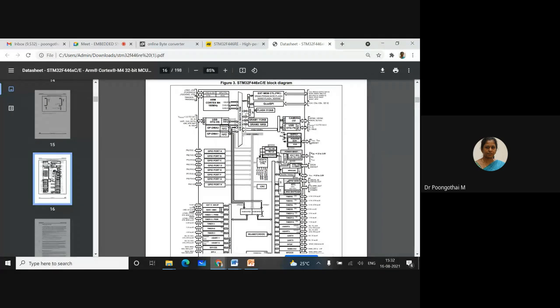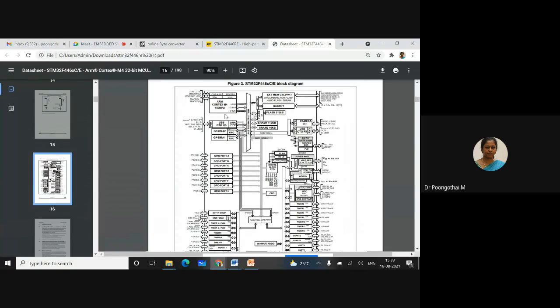All the peripheral devices are connected to this particular processor. The CPU engine interfaces to the ST implementation by using three bus interfaces: I bus, D bus, and S bus. This is the software IP format given by ARM, the intellectual property format, and these implementations are done by ST. They both meet at these bus interfaces. All the devices communicate with ARM Cortex M4 through this bus interface.